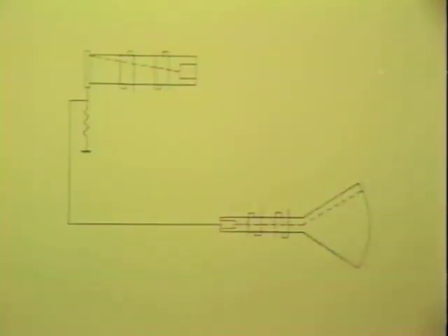The beams are synchronized, or kept in step, horizontally by using the same signal to simultaneously drive the scanning coils around the camera tube and the picture tube. The actual signal is generated in an oscillator. The vertical movement is produced in a similar manner. Another oscillator produces a signal which is simultaneously fed to both sets of vertical coils around the tube and the picture tube. The horizontal coils produce the left to right scan of the beam and then the fast retrace. The vertical coils produce the slow downward movement of the beam until it reaches the bottom, and then the faster vertical retrace to the top.